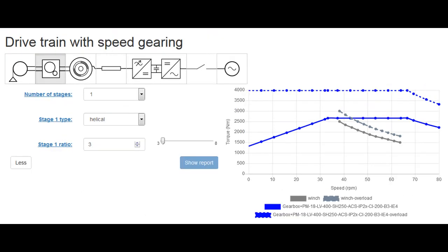And then we play with the parameters of the components as usual, trying to minimize the cost of the system. Then we may choose a topology with the gearbox, and we do the same again, so we can play with the gear ratio to see how the cost of the gearbox changes and how cost of the motor changes, and come to optimal design. Again, this has been done for only one shape of the drum, so it should be repeated for a few other shapes of the drum to find the optimal shape.